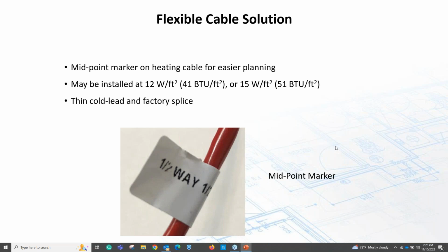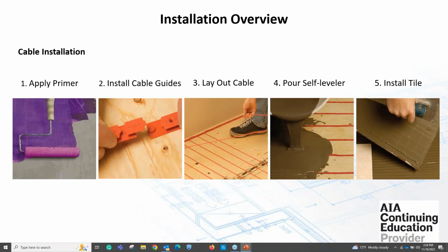A little inside information: if you ever have to pull this wire back up and readjust it, pull it back on the spool. Because if anybody fishes, as a fisherman knows, the backlashes and the twist on that wire get fairly significant, and it's a mess. So put it back on the spool, don't try to wind it up in your hand.